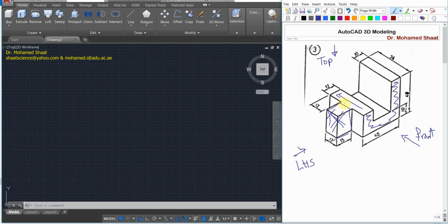So it means that the best command that would be used for this case will be the extrude command. In the Extrude command, if you remember, your objective is to have a two-dimensional sketch as a single loop, a single sketch, a single object of this face. Then I'm going to extend this face in this direction with the 36. So your objective is just to draw a two-dimensional sketch for this face. Then you're going to extend it with the 36